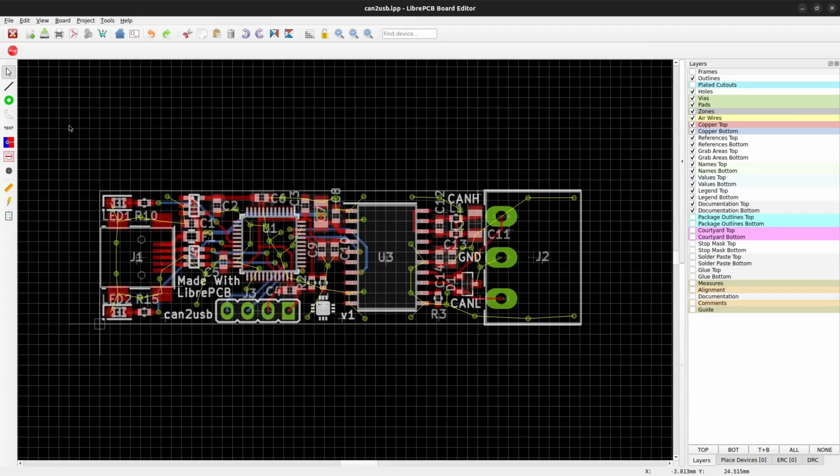Copper planes, or sometimes called copper pours, can be added to fill an area with copper of a particular net. A typical use case is to add a ground plane and maybe also a plane for the supply voltage. They are useful for shielding reasons, to create low impedance connections, or just to simplify connecting many pads. In fact, planes can be used instead of traces to connect pads with each other.